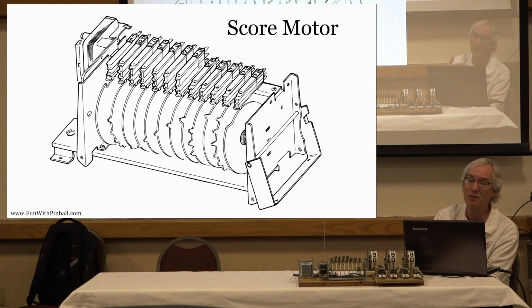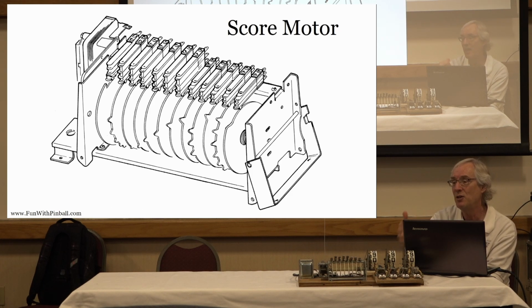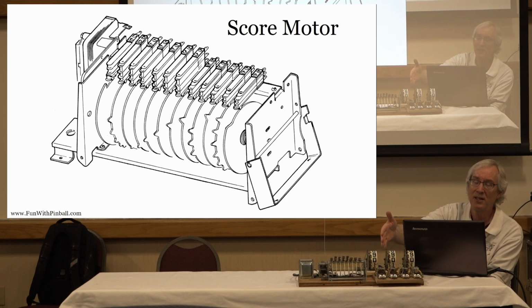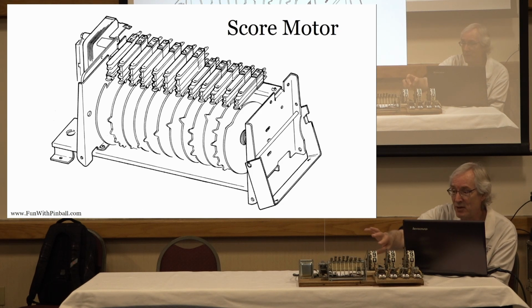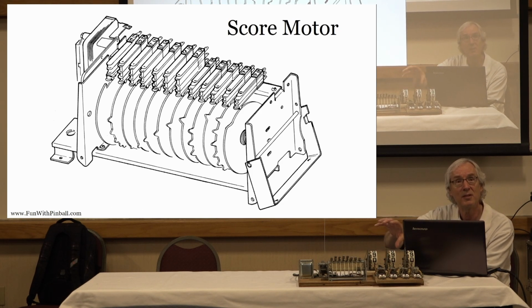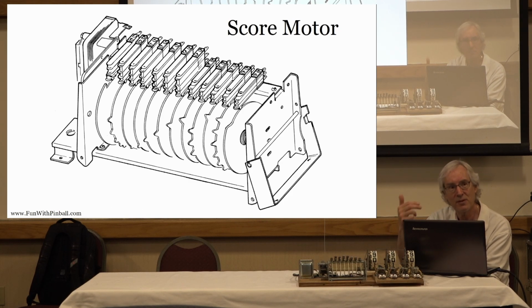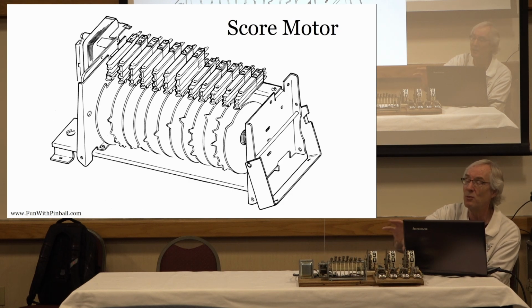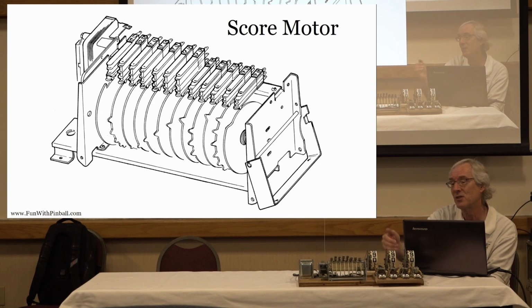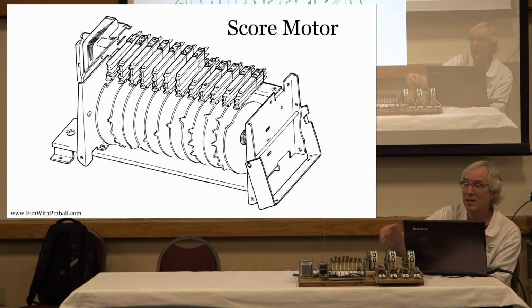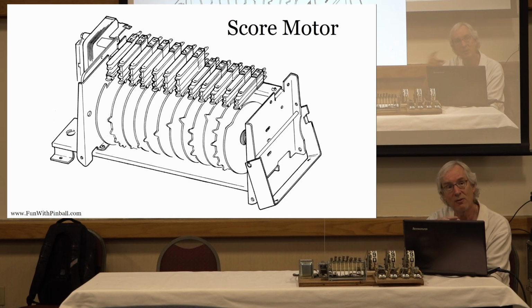Well, if the motor keeps running, it might be that one of these score reels has not reported home yet. And you might think that's a bug. You might think, why doesn't it just send out 10 pulses and stop? That would work on a new game. But an older game that has some wear or some dirt, maybe you have trouble getting past 9 into 0, and maybe it takes 3 or 4 tries. Well, that's why the motor keeps running. It says, okay, I'll give him a second chance, I'll give him a third chance, and eventually it will walk to 0 if you give it enough pulses. So I think that was done by design to keep the motor running until it has seen from each individual score reel that they're all back at 0.